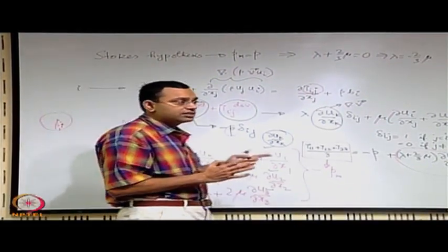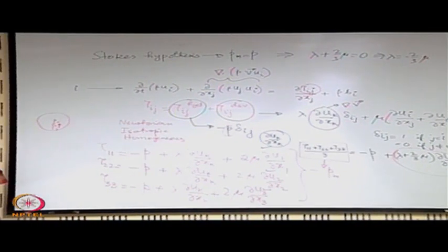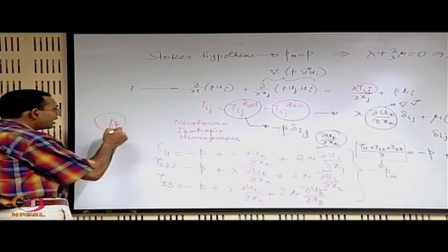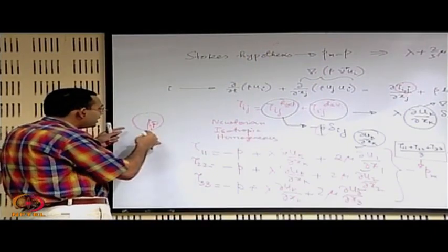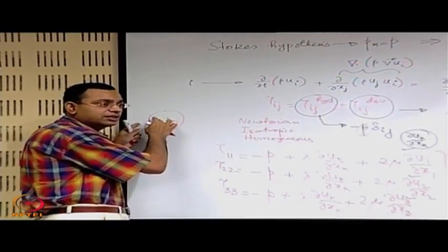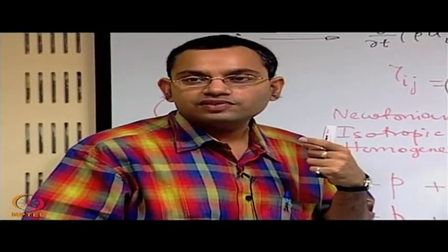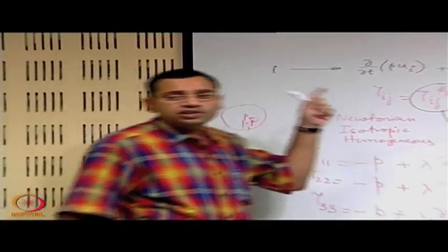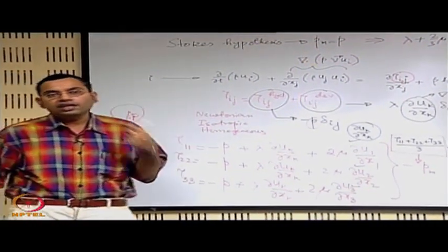But for most of the practical applications that we are concerned about, the Stokes hypothesis works, because usually the relaxation time scales for fluids are very fast. And usually the changes which are imposed on a system are not faster than that. So whatever change is imposed on a system, at least locally at a point it tends to attain equilibrium, and that is called local equilibrium. It is not a global equilibrium, that means it is not that throughout the system at each and every point properties are the same. But at each and every point it attains an equilibrium where its properties are related by the equation of state, and eventually the interconversion from one mode to the other is possible, that time is available, and that is why the Stokes hypothesis works for most of the problems. Only for a few rare cases where the change is so rapid in terms of the time scale, there it may not work, otherwise it is working.